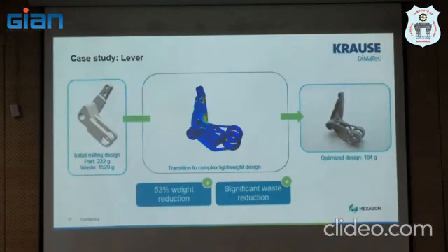Because recently we have done one with ISRO, printing aluminum alloy with ceramic. We were not able to even print a 10 by 10 coupon. So we have tried all of this. The material requirement is that it should have some thermal conductivity plus the aluminum property. Now when I try to develop a material, material development is a big task when it comes to metal. It is not that easy. For a composite, as you rightly mentioned, we have a tool. It will say that this is the required property, and you choose any material or you develop your own material.